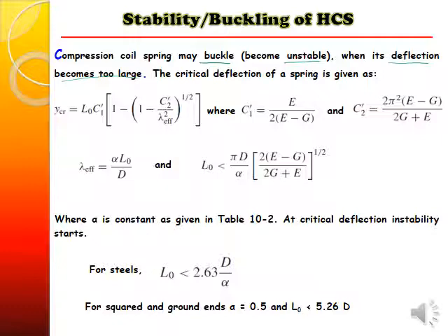In other words, the spring is like this, and when you apply the load, if I just fix it, it may go like this. It's buckling, and I need to prevent it in my design. So I need to find out the critical deflection of a spring.